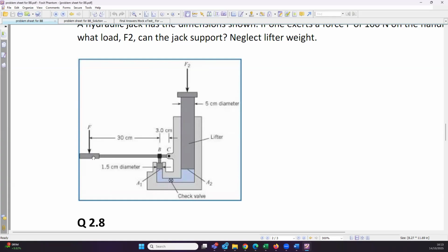To use the moment, we know that moment is force times distance to the pivot point, okay? That's where students get confused. They always forget that the distance is from the point of action of the force to the pivot point. That's very important. You have to consider the pivot point. Now if you look at the force balance here, if all the moment on this system is 0, it means that the system is in moment equilibrium.